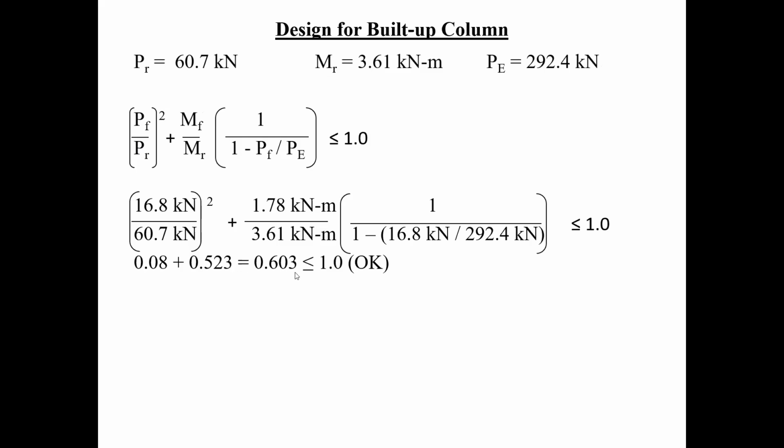You see, so therefore, what this tells you is that load combination 4 is a little bit more severe in terms of how it's going to impact the resistance of the material than load combination 3. So the wind load here brought the ratio up to 0.643, and we're okay. So that means that as far as being able to resist both wind and snow load, this 3-ply 2x6 would be ample, because look how much more room we have until we get up to 1.0. So this gives me a lot of breathing space in terms of making sure that I can have additional resistance.